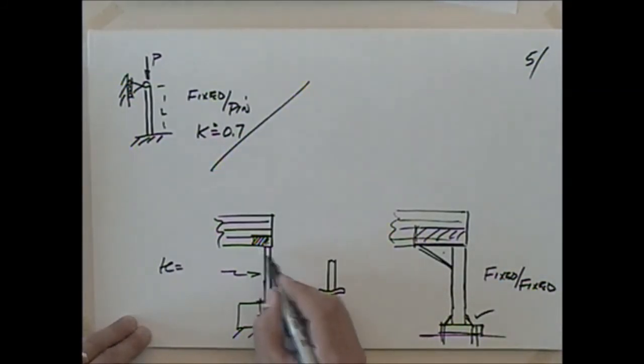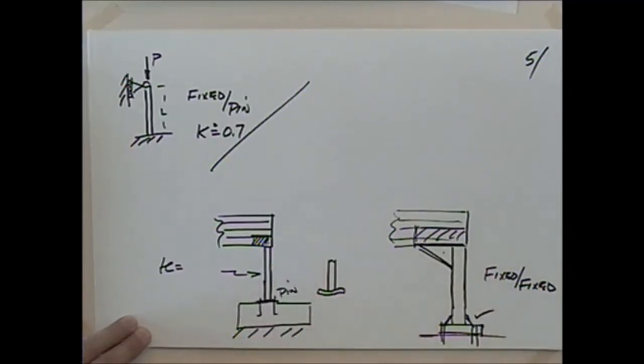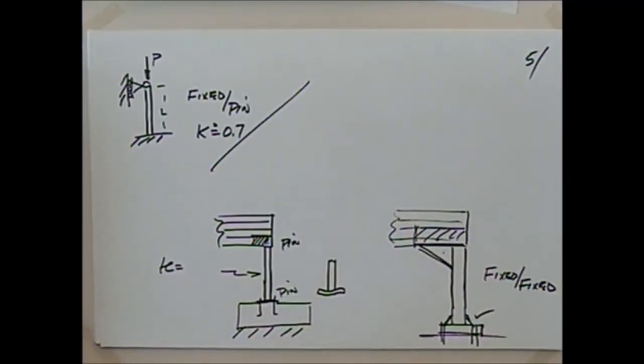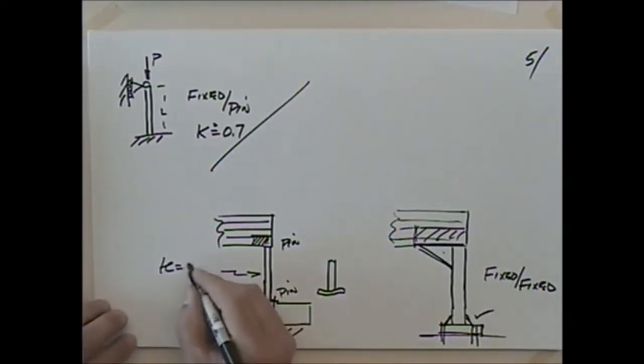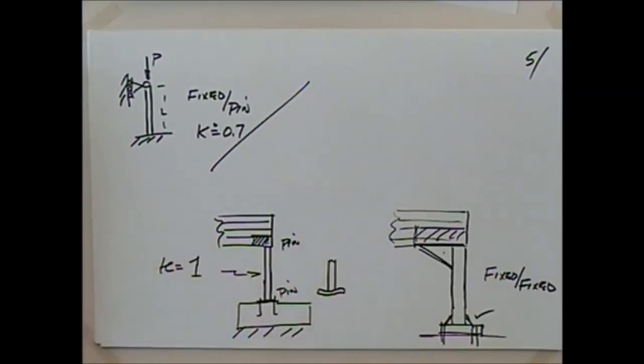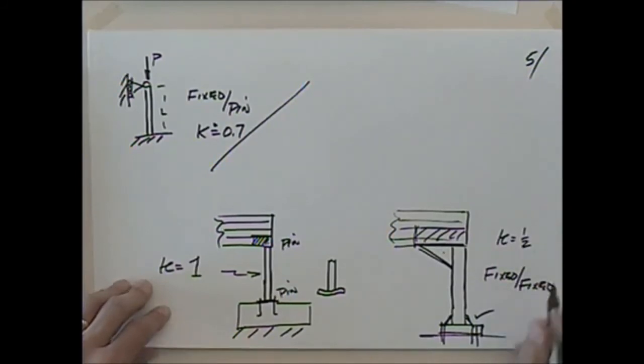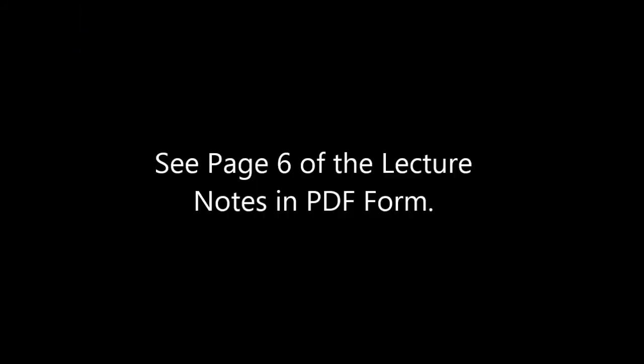And up here, I don't have a lot of gussets. Could we get some bending and some rotation up there? Probably. So I would think that we probably have a pinned-pin connection there, in which case we're going to be what? 1.0, whereas what were we if we were fixed? K is equal to a half, or from our table here, if we are pinned, that's that one. If we are fixed, we're a half, or maybe 0.65.